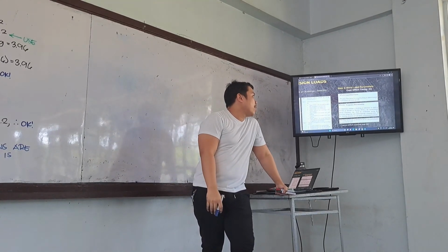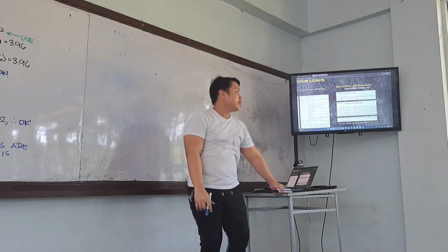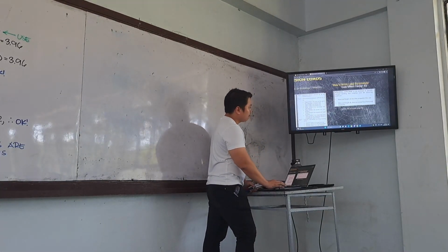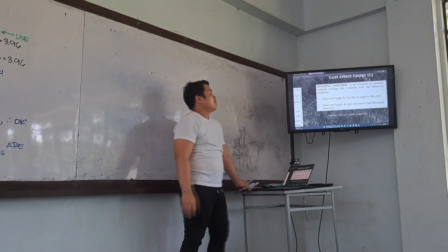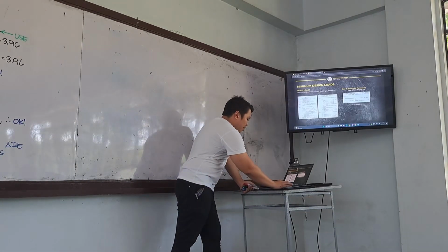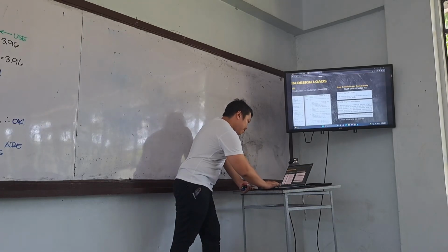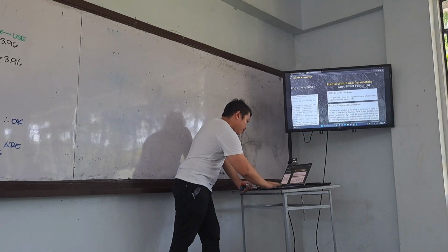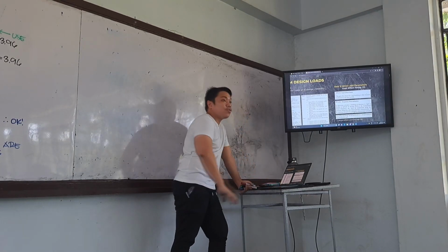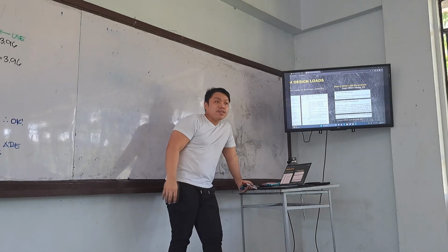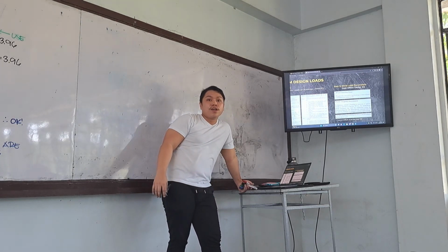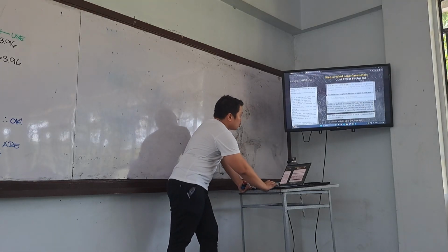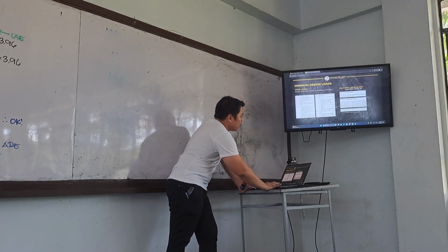So how can we identify if our building is a rigid building? Let's refer to our section 2.2. If the building is low-rise, natural frequency less than 1 Hz, flexible. So we won't use frequency to determine if the building is rigid or flexible. Rather, we will use this definition, section 207, 8.9.2.